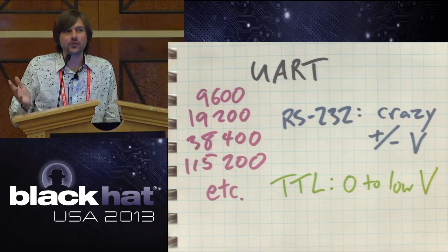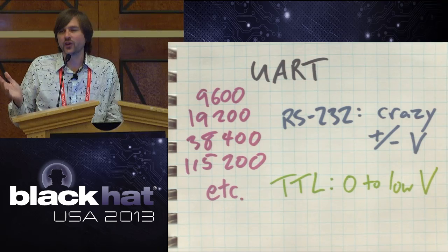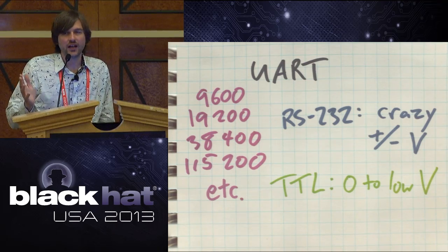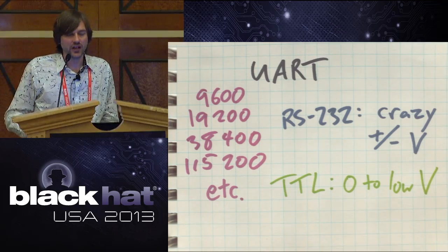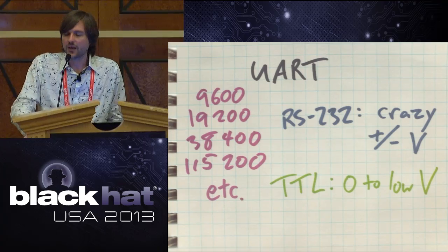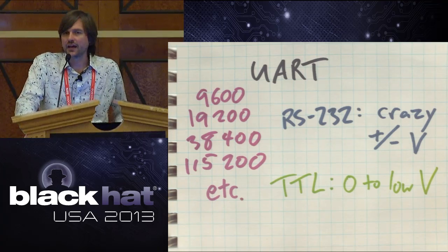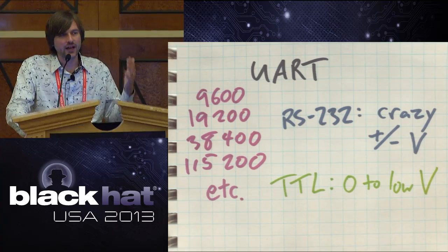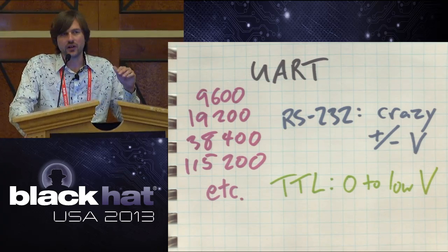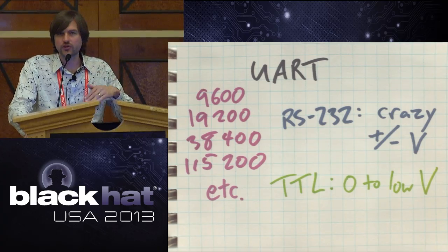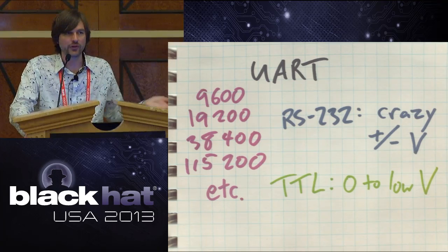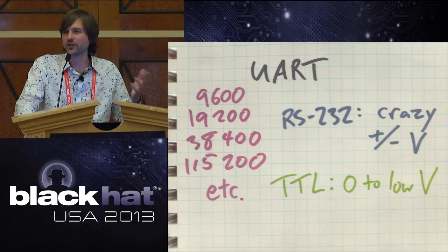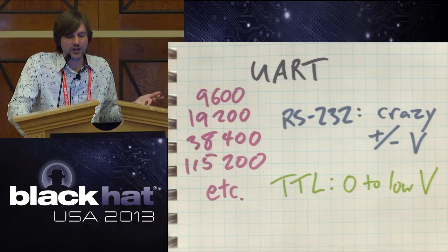And it's a TTY UART, which, I'm sorry, TTL UART is what I mean to be saying, which we've kind of abused the term TTL over the years, but it means that it's a serial port that operates at logic levels. So like voltages from 0 to whatever the operating voltage is of the chip you're talking to. So 0 to 3.3 volts, 0 to 1.8 volts, might be 0 to 5 volts.